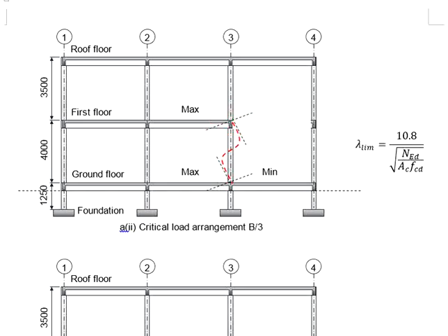The meaning of monolithic is that we assume all the members are perpendicular to the joint, that means 90 degrees to the axis of the joint. Because of the rotating moment here, the joint goes inclined, and the column will have to be 90 degrees to the inclined axis of the joint. This leaves you with the column going in these directions.